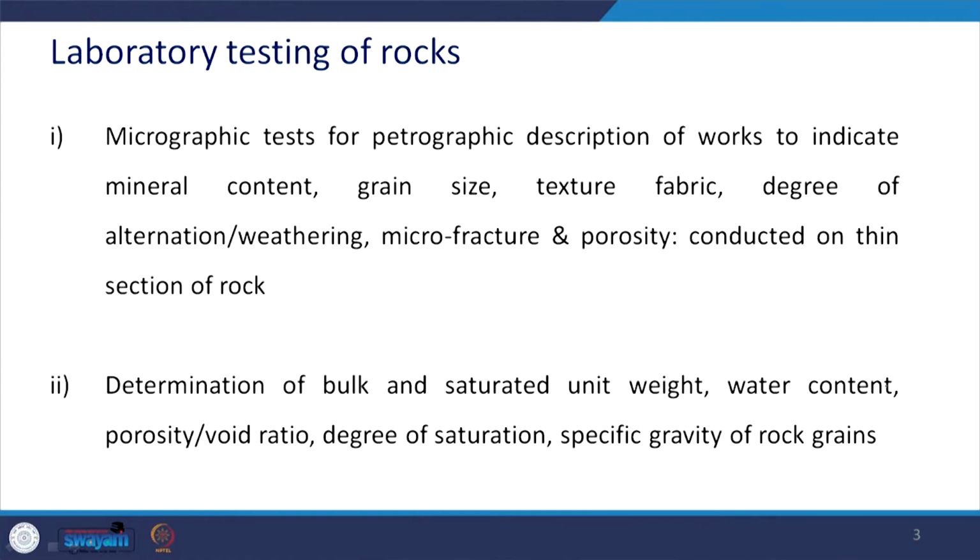So, basically, micrographic tests are for petrographic description of rocks to indicate the mineral content, grain size, texture, fabric, degree of alteration and weathering, microfracture and porosity.